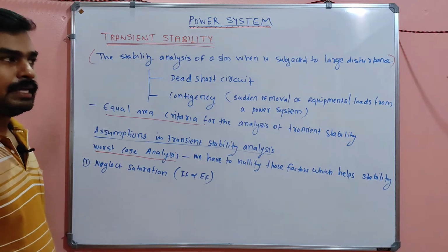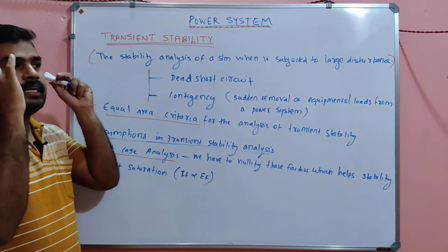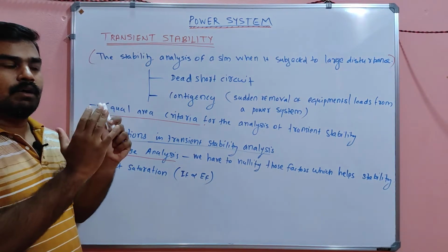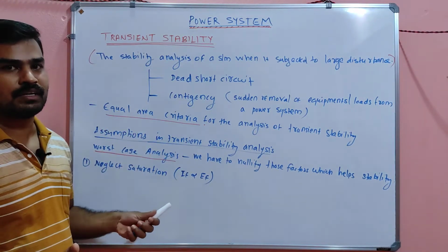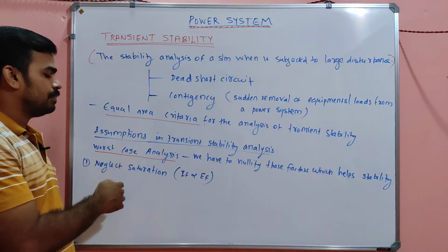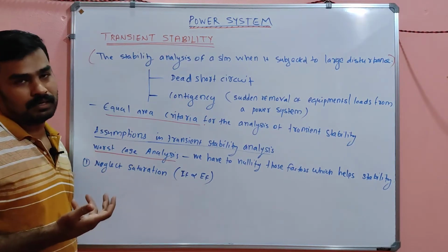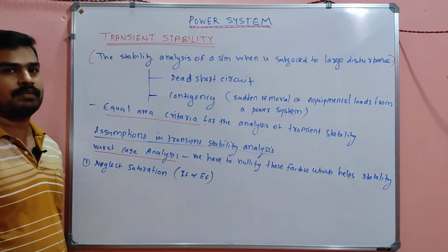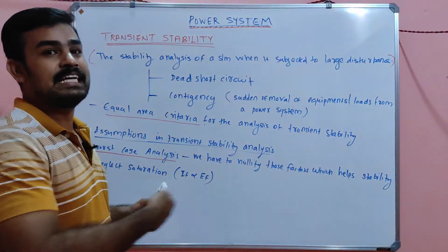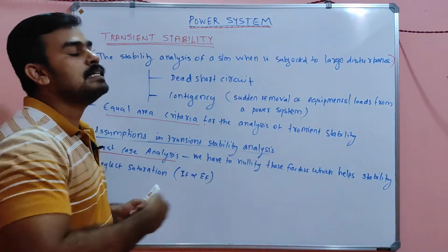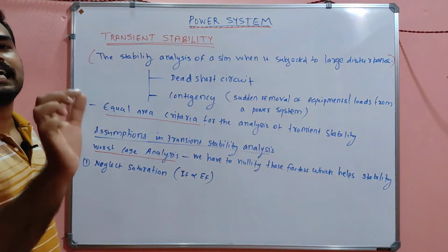Okay, so actually the saturation point, if we include it, means we are considering the alternator when it is saturated. If the point of saturation is included in this analysis, then what is the point of saturation? At a particular point, even if we are increasing the field current, which is a type of change in input, there will not be any change in the output. That is the meaning of saturation.